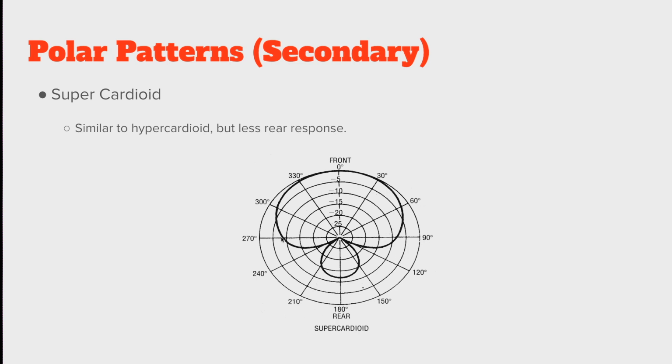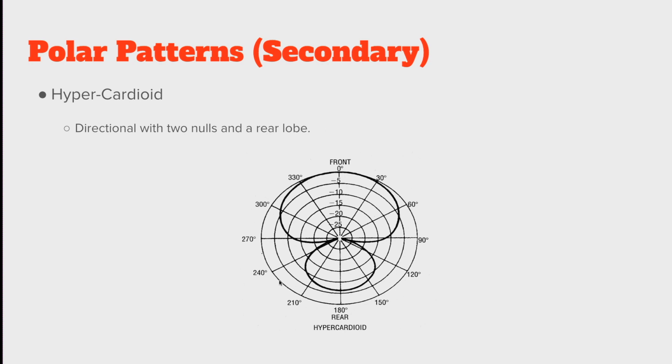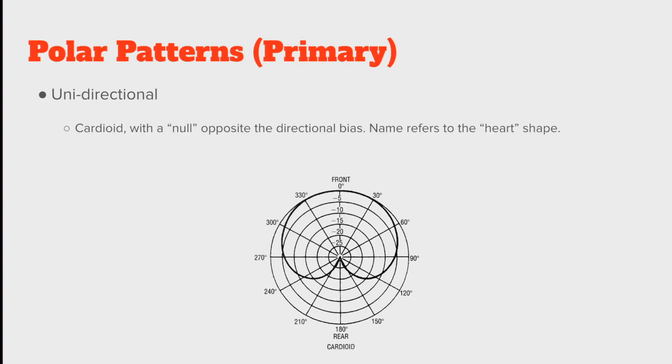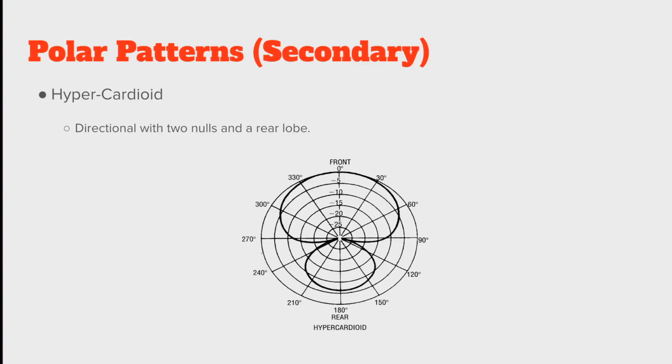And in doing so, that usually tends to widen out the cardioid shape on the forward lobe, on the front lobe, and obviously attenuates the rear lobe quite a bit. It also pulls those nulls a little farther towards the 180 degree point, though obviously nowhere near 180 degrees, but a little bit wider than what we had here and quite a bit wider than what we had in our bidirectional.